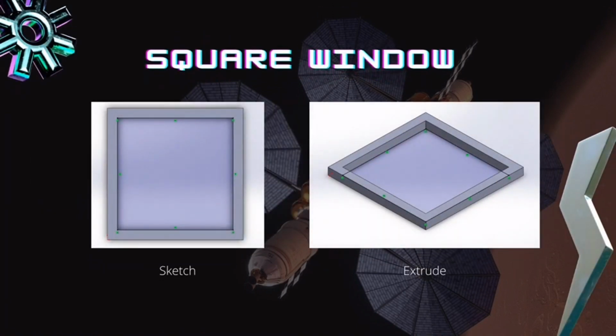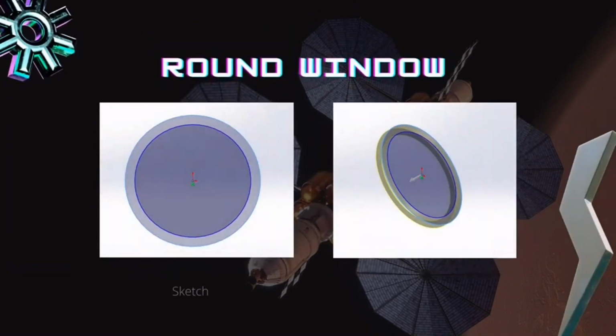For the square window, we first drew an inner square on the front plane in sketch mode. Then by using the offset tool, we select all the lines of the smaller square, set the dimension, and draw the outer square. After we got the shape, click the edge that we drew just now and extrude in features mode.